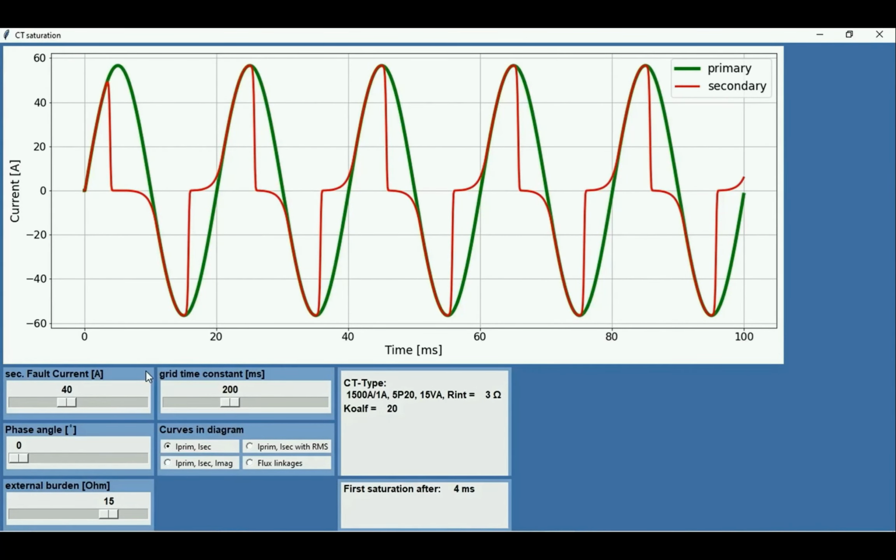And you see if we have 40 amp, that means double current, we run into a saturation error, then we see a completely different picture. You see here in green that what we should measure, and in red that what comes out of the circuit because our magnetizing reactance sometimes draws a lot of current. So you see it typically follows the green curve until we reach saturation point, and then it goes down, and then the same thing is repeated.